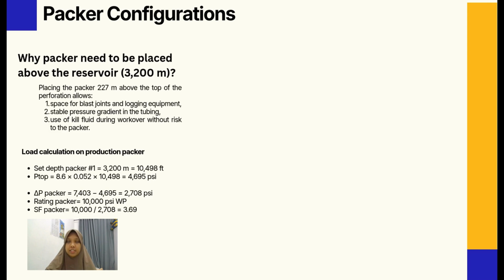And then here, for the elastomer seals, we chose HNBR. Why? Because NBR fails at our 135 Celsius well temperature, EPDM lacks H2S resistance, and AFLAS is simply not economical. So HNBR is perfectly balanced: thermal durability, H2S and CO2 resistance, and cost efficiency.